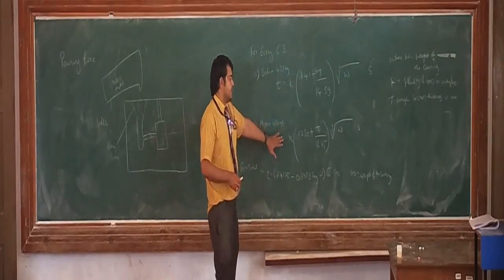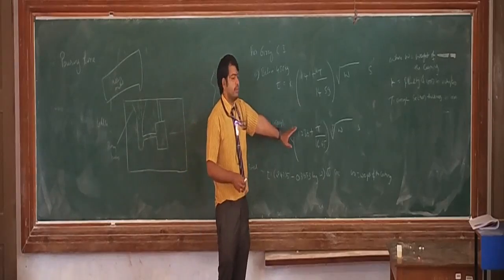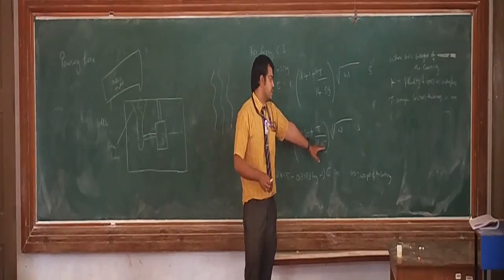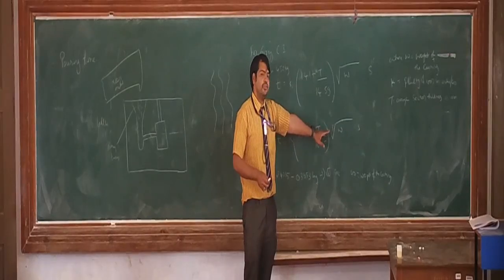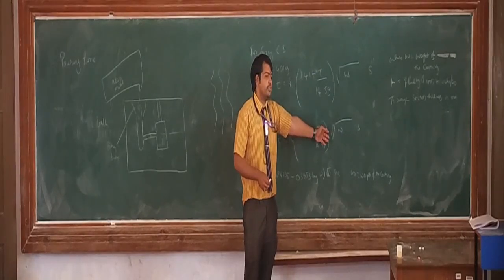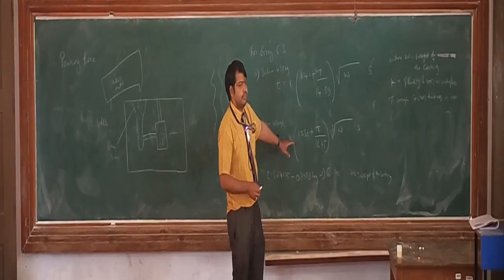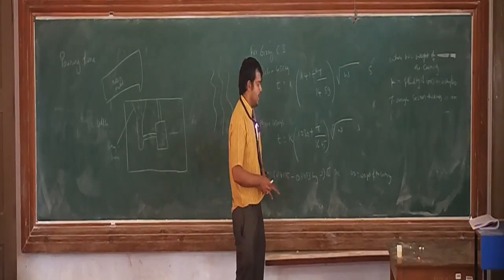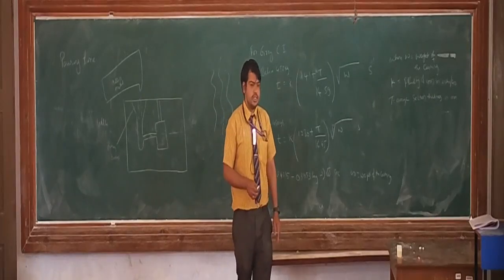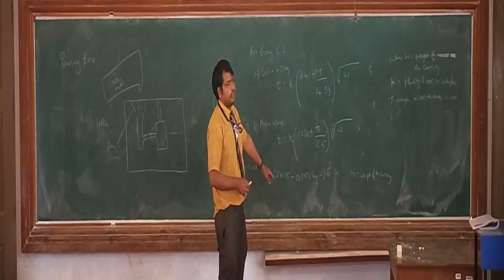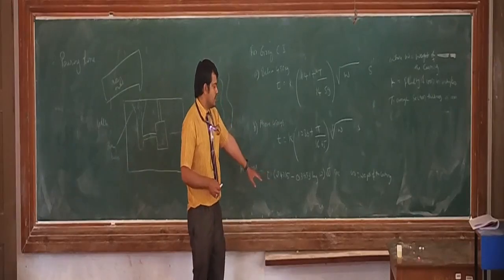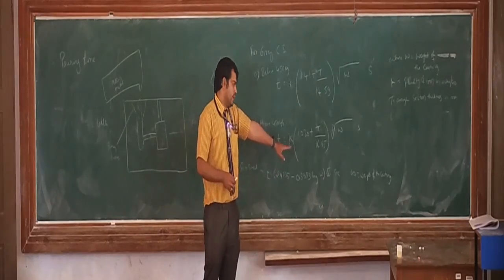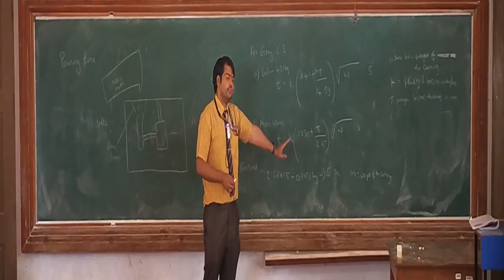Above 450 kgs, T is K into 1.236 plus T divided by 16.65, into cube root of W, where again K is the fluidity of the iron in inches divided by 40. Then the pouring time for steel is given by 2.4335 minus 0.3953 log of weight of casting, the entire thing multiplied by the square root of weight of casting.